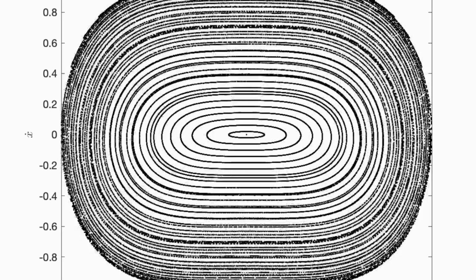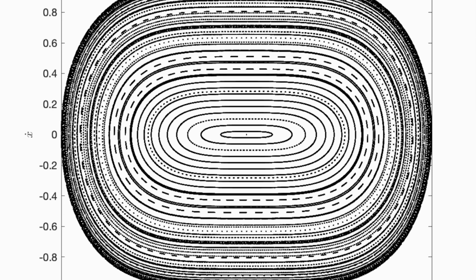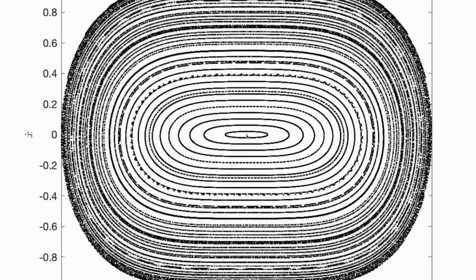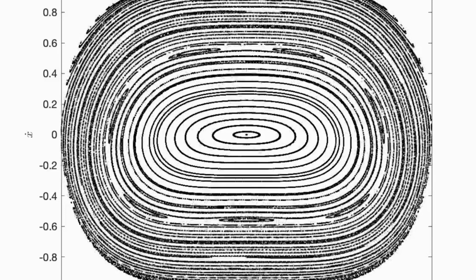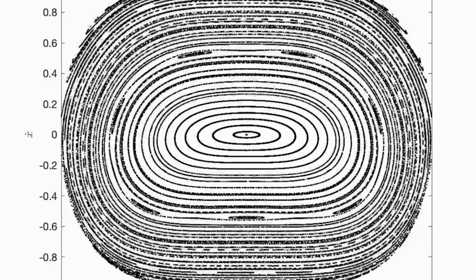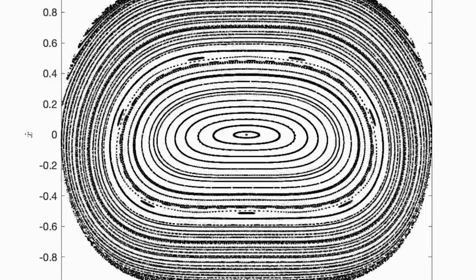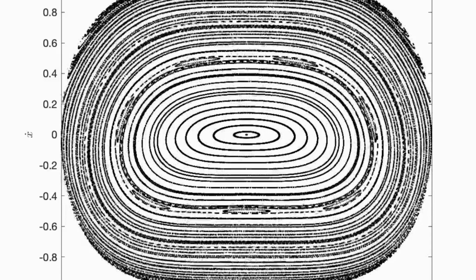This here is the Poincare map for the NO. Starts off with just a single fixed point in the center here. We're going to go frame by frame through this, and you can see those orbits are getting tighter and tighter and tighter. There's suddenly now an emergence of what looks like a 7-to-1 internal resonance. Again, damping will tend to kill this type of behavior. Here again, there's a 7-to-1 internal resonance.